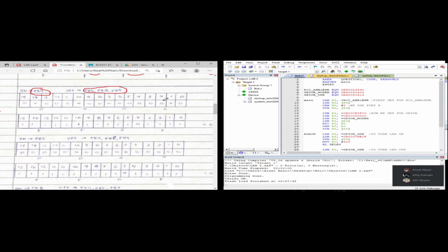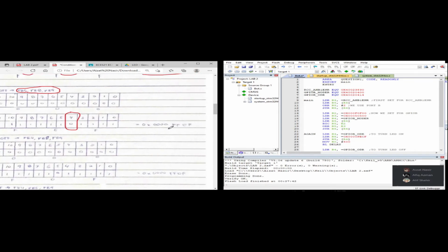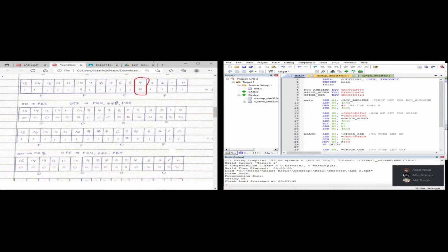In order to do this, we will be putting 0 at port 4 as the circuit is active low. And the other ports we will use 1 to turn off the other LED and other ports. So as a result, we will obtain the value 0x0000FFEF.